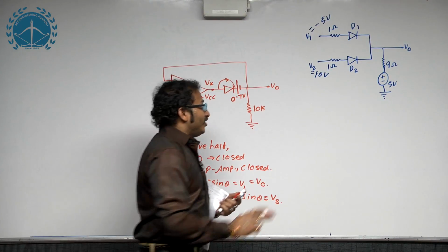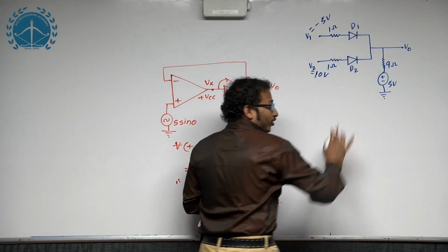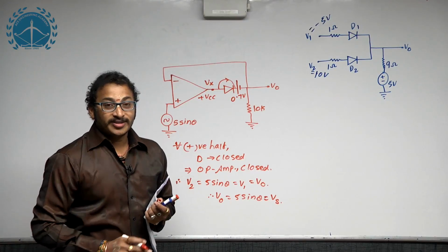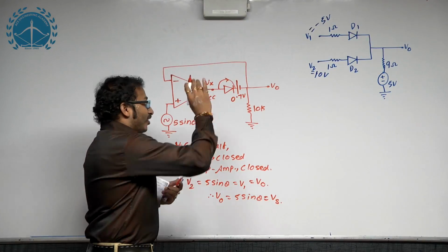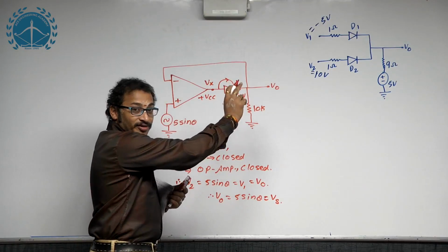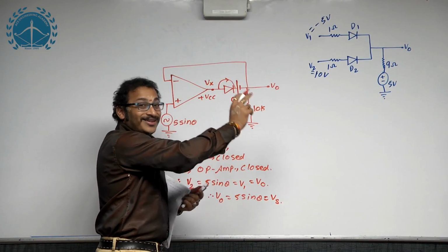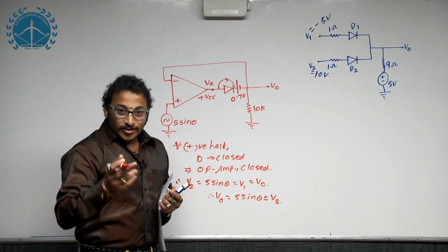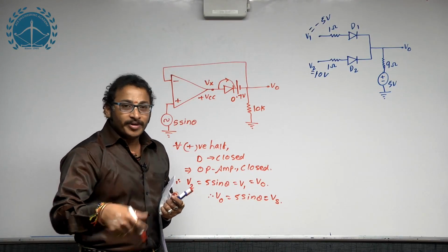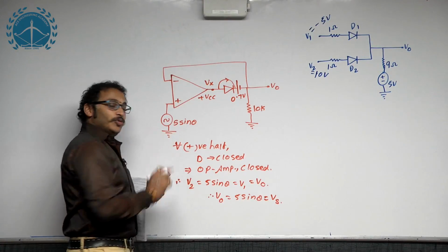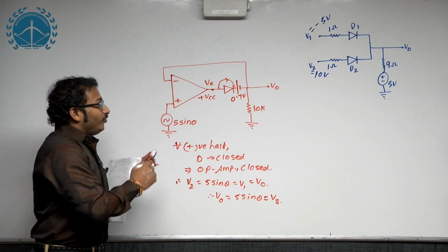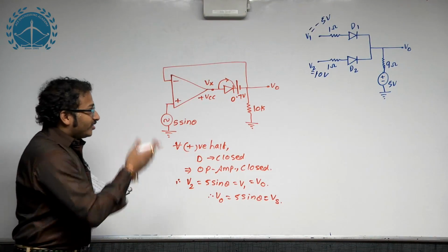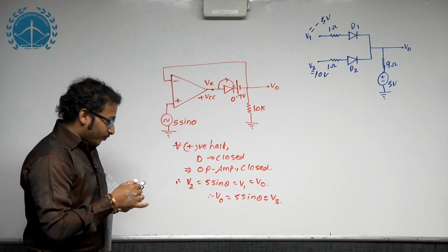So my dear students, diodes D1 and D2 are given in the circuit, and he told us those two diodes are precision diodes. Understand, they are not simple diodes. Each individual diode is connected with an entire operational amplifier circuit. So due to the op amp, a practical diode behaves like an ideal diode. You need to understand this clearly, then only can we proceed with the precision or super diode. Now let us start the answer for the given question.